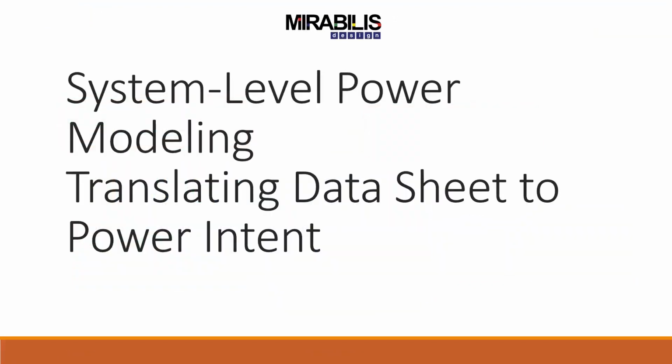Okay. Now that we've seen the entire methodology, let's look at what we want to achieve out of this particular system. There is a first case where we didn't have any information. We're building up the system from scratch, and we start adding information based on the process technology, using the tech data files to figure out the power for each component. There are always scenarios where you might already have a prior generation design, or you might be purchasing IPs or chips from third-party vendors that you're now trying to integrate into your system.